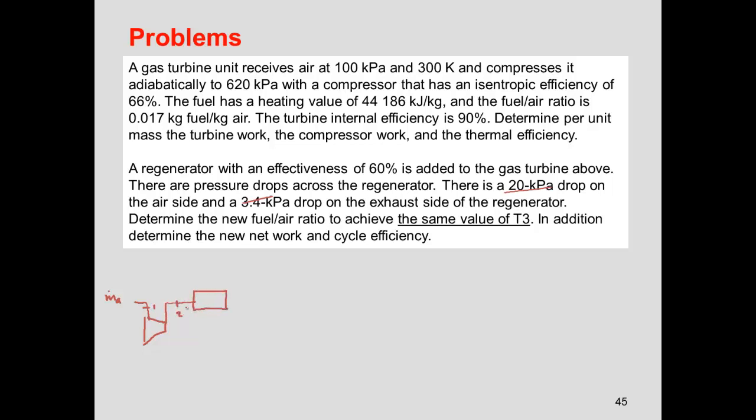This is our state 2, we have this air, and then we introduce a mass flow rate of fuel. Because of this combustion, we finish at state 3, and introduce this into a turbine. State 4, we connect the turbine to the compressor, and we have a net output.